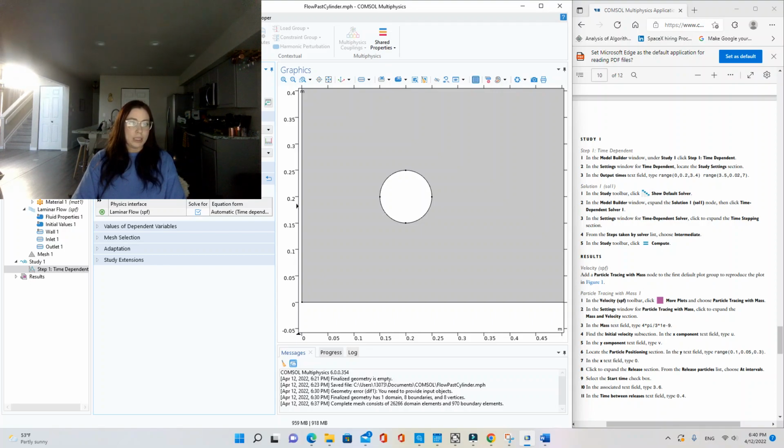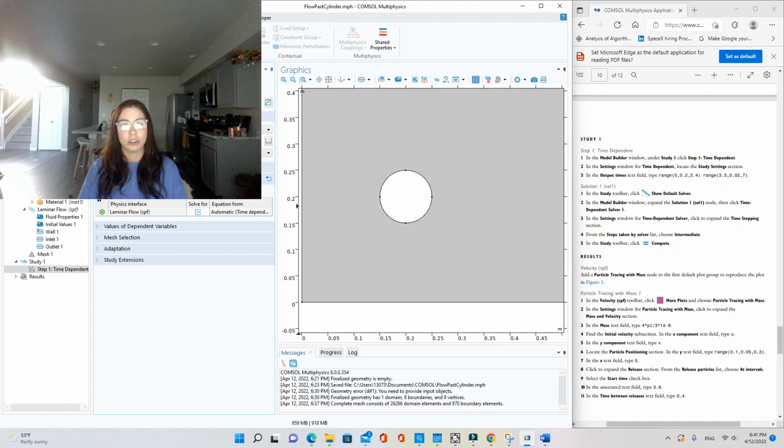Okay, so basically it's doing large time increments on the startup in time 0 to 3.5 seconds, and then we really want to look at the steady state. So we're getting a time dependent solution or transient solution, but we're not going so computation heavy on the startup portion of it. We're sort of skipping over the startup portion in larger steps.